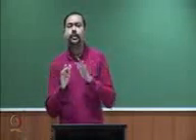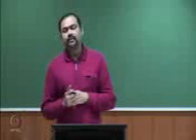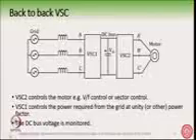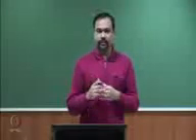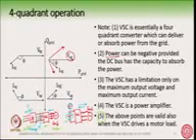Okay, so within that you can find out yourself how much is the maximum power that can be delivered by the VSC. So the VSC is always defined in terms of voltage and current usually. Okay, so then you say that this is the maximum apparent power that the VSC can deliver. It's the S of the VSC. So you can change the P and Q, you can adjust within your limits. So the maximum apparent power that the VSC can deliver is denoted.